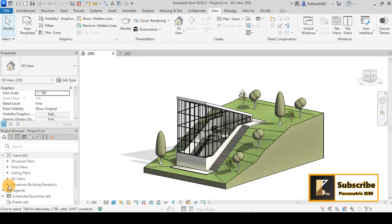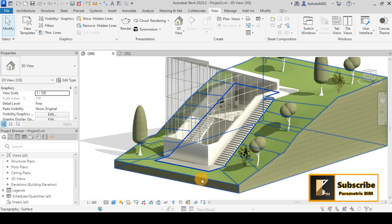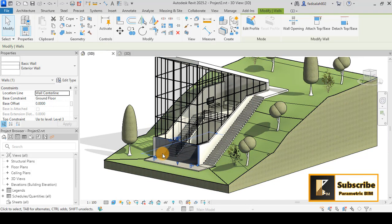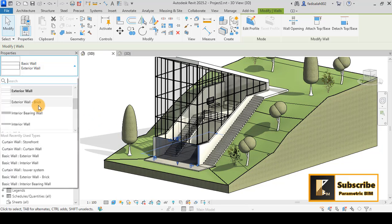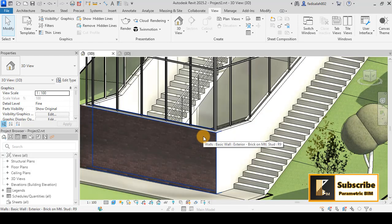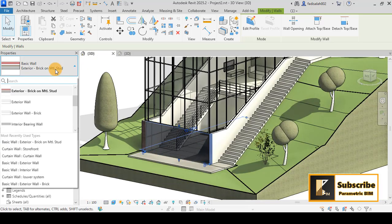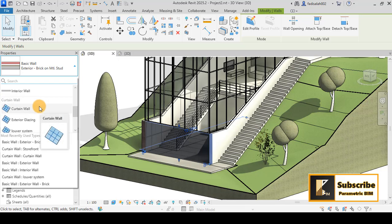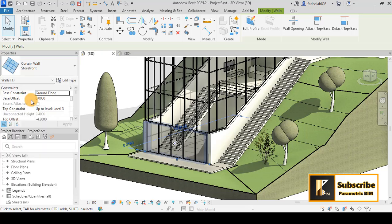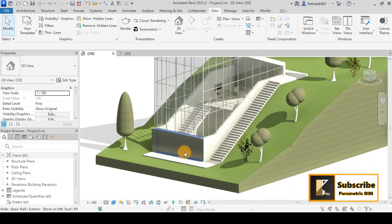So now this is enough about the project browser. Let's talk about the properties here. As we talked before, this is the properties of any component of Revit you have selected. Now I am not selecting anything, so this is the properties of the 3D view. But for example, if I come here and select this one, you can see that this is the properties of the wall that I have selected. So I can change the type of the wall from here. If I select here, you can see that this wall type has been changed by selecting and changing its type from the properties. Maybe you can change it to curtain wall or anything you want. So from here you can control the properties of any component that you have selected.